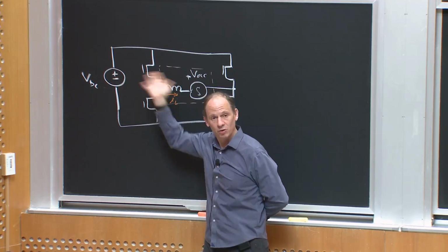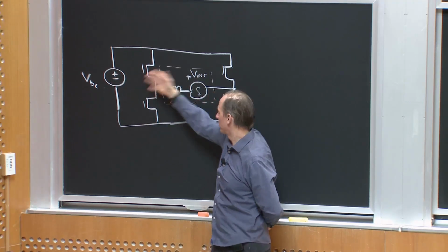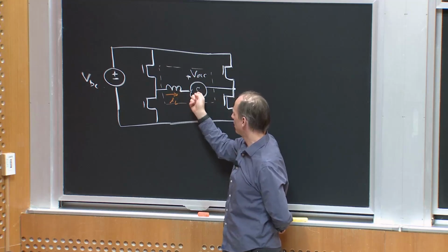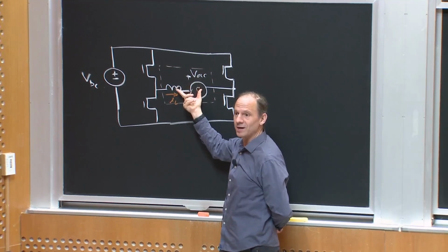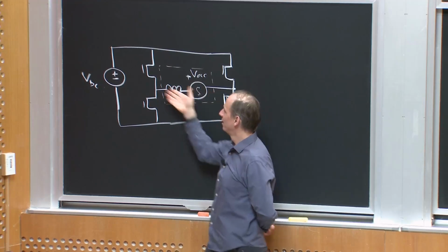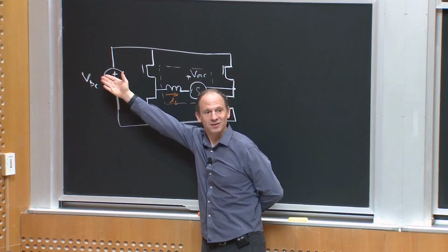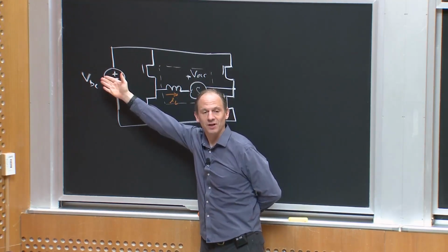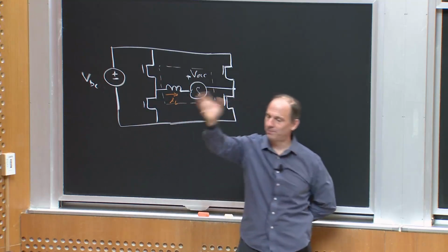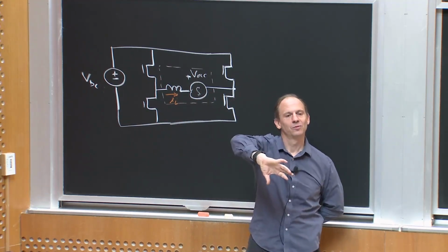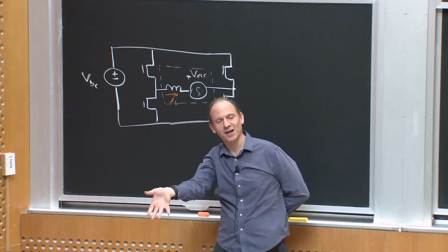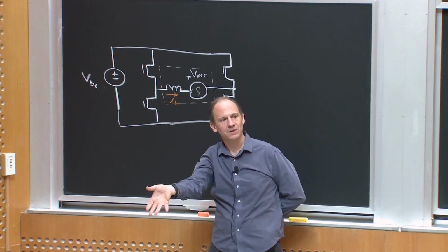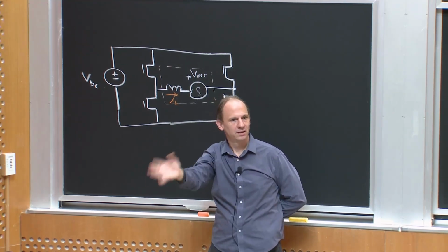Or maybe this is a motor drive, right? Sometimes I'm driving power into the back EMF of the motor to generate torque, and sometimes I'm regeneratively braking and absorbing power from the AC side back to the DC side. So I can either generate positive torque with respect to speed and deliver mechanical power, or absorb mechanical power and slow down. Any questions about that?